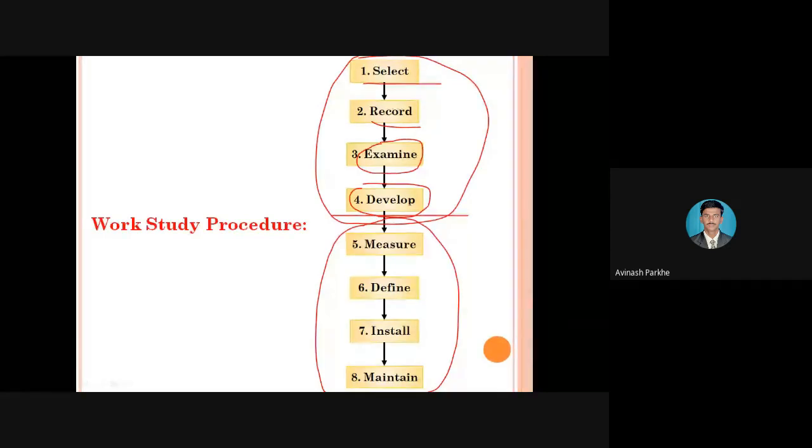And from step number 1 up to step number 4, whatever process we are carrying out, that particular concept or process is called a method study. And from step number 5 to step number 8, that concept is related to work measurement.